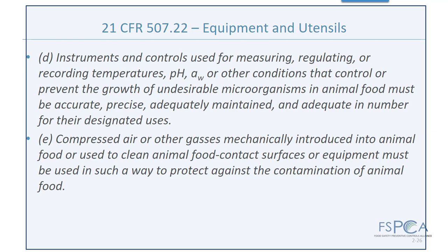And in this particular facility, the incoming ingredient bay or drop area was directly next to the air compressor that was used to dry clean the rest of the facility. And so as the corn was being dropped off at the facility, all of the corn dust, which is where the aflatoxin lives, was being sucked into the air compressor and then blown all over the rest of the facility.